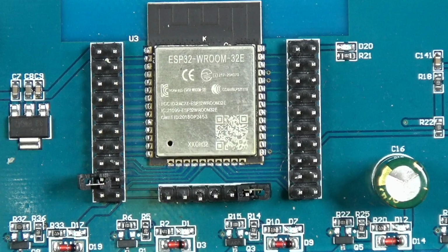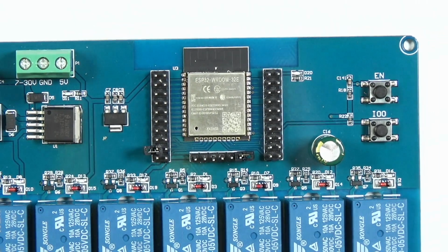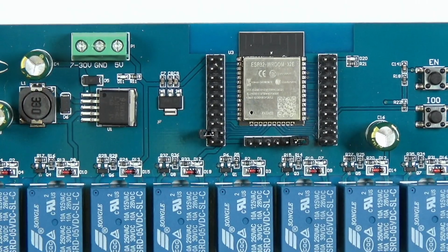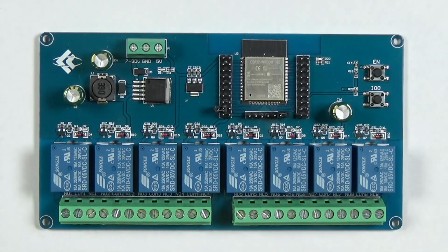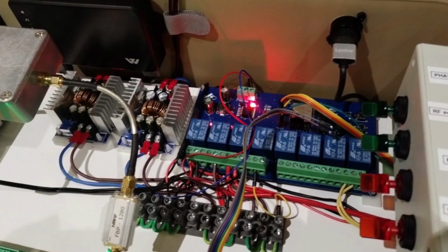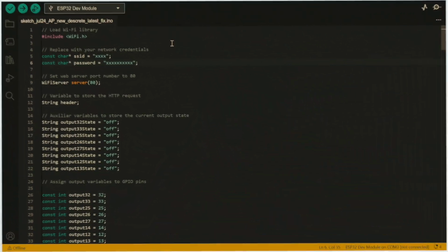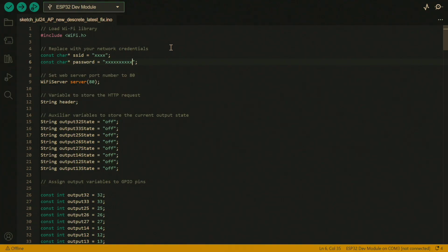One of these boards catches my attention. It has integrated relays built right in. Now, this board is particularly useful because it allows us to control multiple relays with a single microcontroller. In fact, I'm using this exact same board in our own RTV transmitter project. Let's take a closer look at how the relay control works on this particular board.